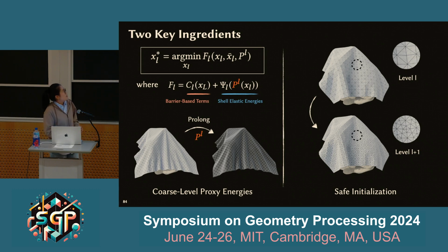It's because now you don't have a fixed topology to operate on. All the simplification, or mesh coarsening steps, are computed in a fine-to-coarse manner. So you have to keep track of all those edge collapses and then reverse those operations when you're doing upsampling afterwards.